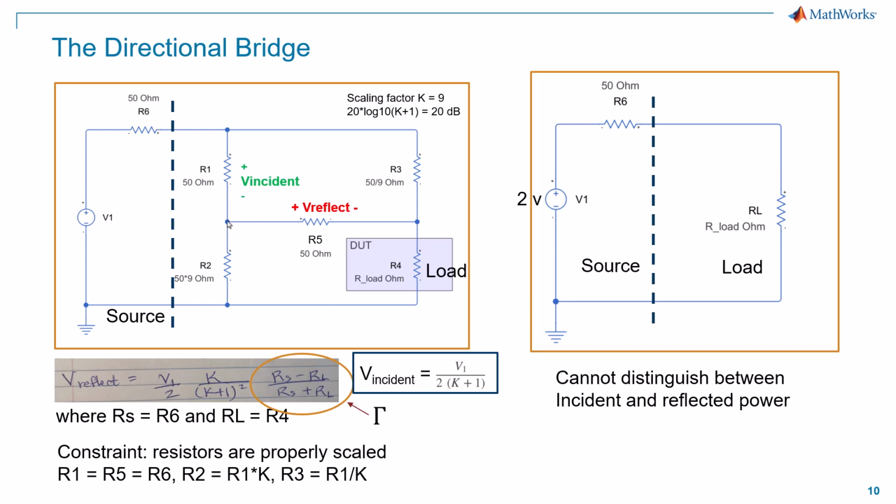Therefore, you're going to get the same voltage on the left side of R5 as on the right side of R5, again, with respect to ground. And therefore, if you have that same voltage, you're not going to have any current through R5. It's going to be as if R5 were not even there. Now, in that case, because, again, the ratio is 1 over 9, you're going to get 9/10 of a volt drop here and 1/10 of a volt drop here.